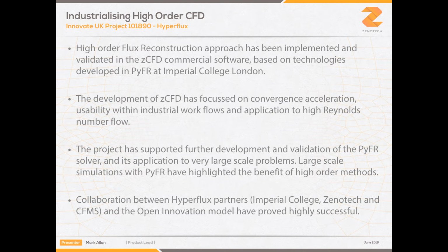So just to conclude then, the high order flux reconstruction approach has been implemented within ZCFD, and we've validated it on a series of canonical test cases. The method implemented is based on the technologies that were developed for PyFR by Imperial College London. The development of the ZCFD solver has focused mainly on convergence acceleration with the aim of using an efficient steady state solver to be able to run unsteady simulations with the dual time stepping scheme.